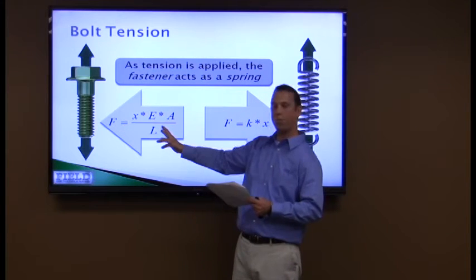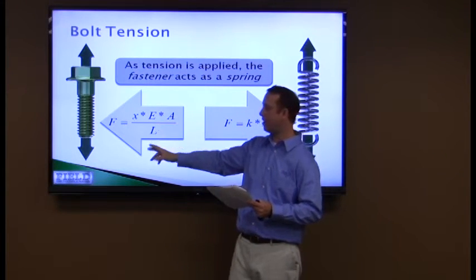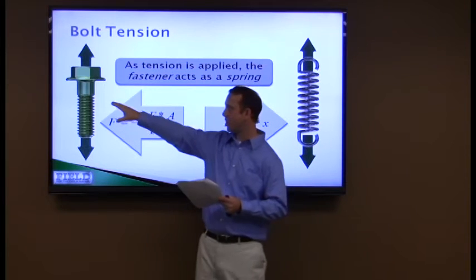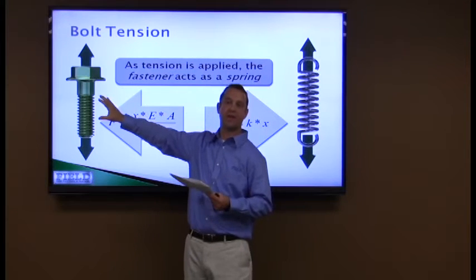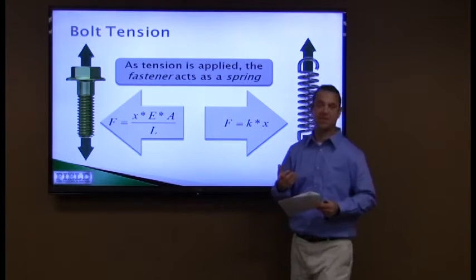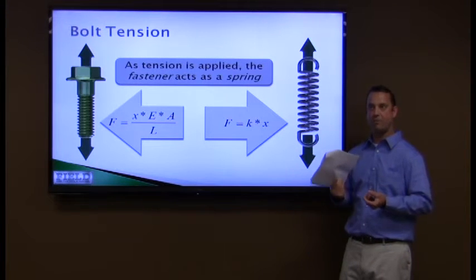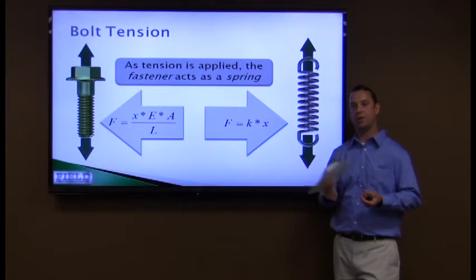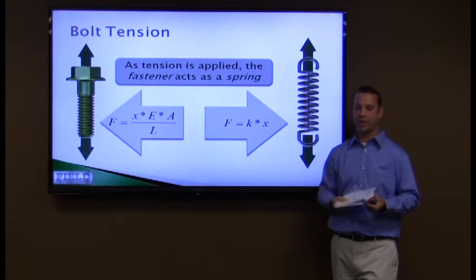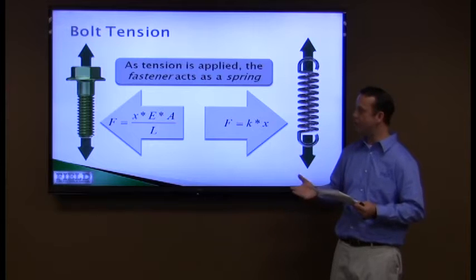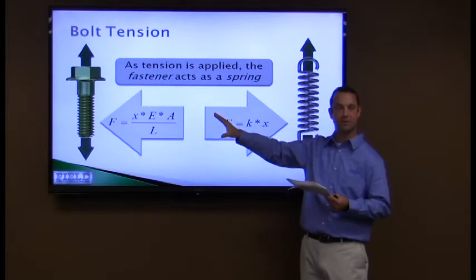So if you were to go from 1 inch of clamp length to 2 inches of clamp length, keeping your force the same, your stretch may go from 5 thousandths to 10 thousandths. And again, we learned in previous seminars that the more bolt stretch you have, in general, the more robust the joint, and it'll withstand the forces of relaxation and bending much better. In general, you want as much stretch in your fastener as possible.